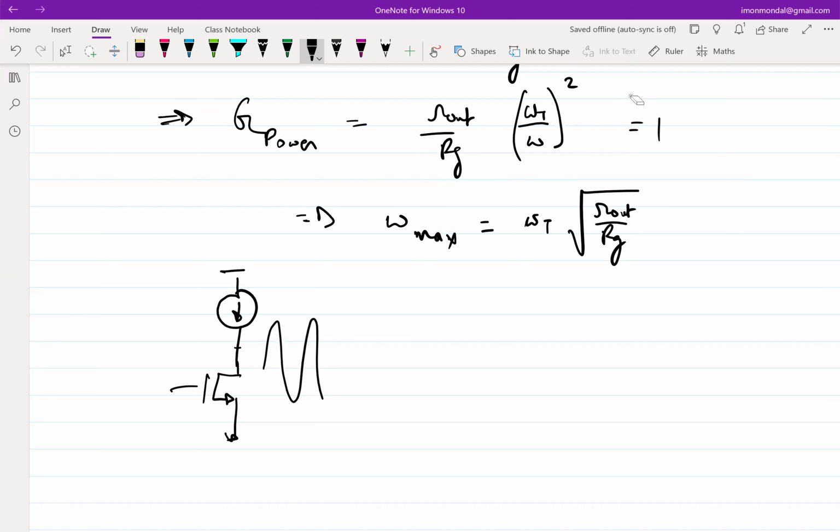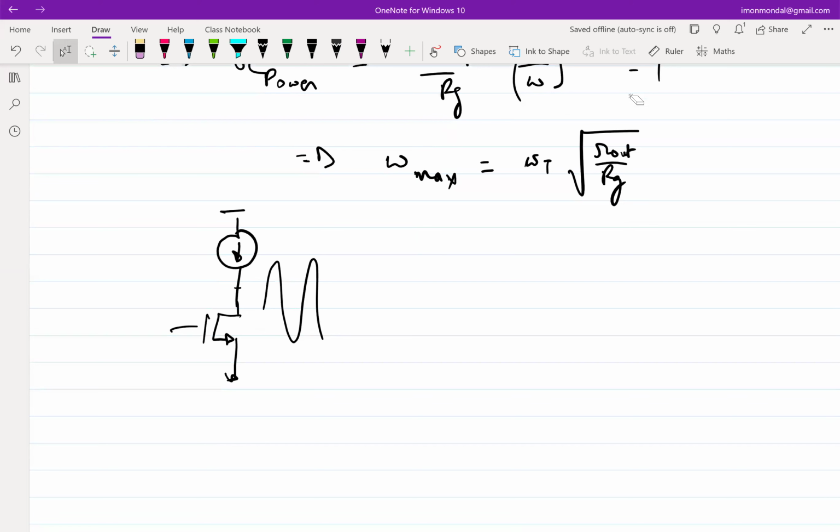Okay. The question is, why does it break down? It goes back to what we learn about capacitors at the beginning of maybe class 12. You have this dielectric, and you have this electric field. Every dielectric has a maximum electric field beyond which it pulls the electrons away from the atoms. So each dielectric has a breakdown field before it punches through. It's no longer an insulator; it punches through, right?